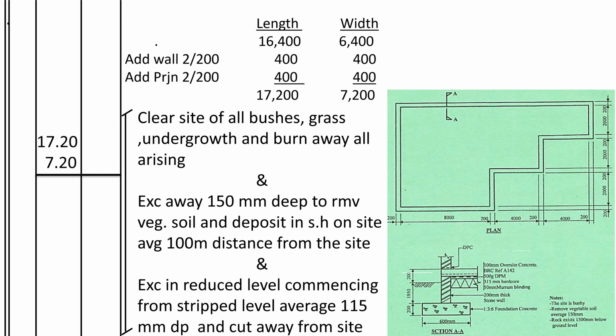Yes, the foundation spread, you learn from it. We get it from the foundation strip. The foundation strip, if you deduct the wall, then you divide by 2, you'll be able to know what is the length of this spread. The red line is the spread on the outside, spread on the inside.